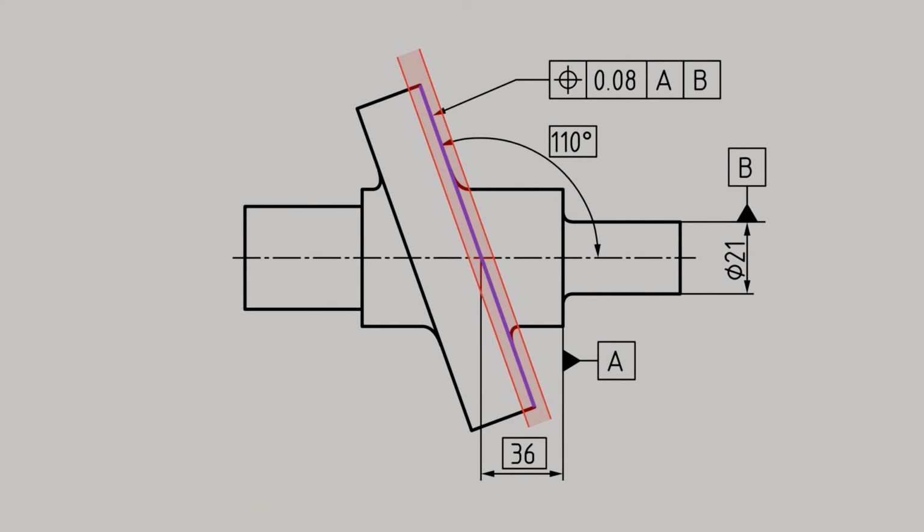This now also limits the location where the tolerance zone must be situated. The median plane of the tolerance zone must be located at the theoretically exact position, which is 36 mm away from the edge of the right shaft shoulder. By tolerancing the position, the form of the geometric feature is indirectly controlled as well. The two planar surfaces that define the tolerance zone directly determine the flatness of the tolerated surface. The unevenness of the tolerated surface cannot exceed the tolerance value of the position.